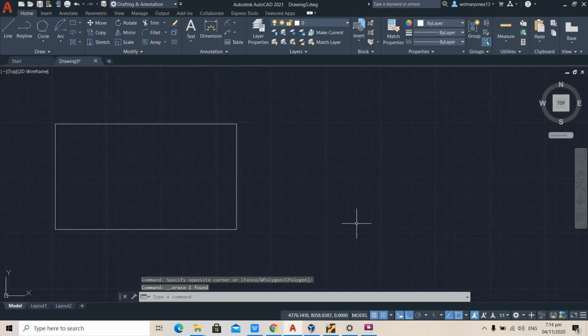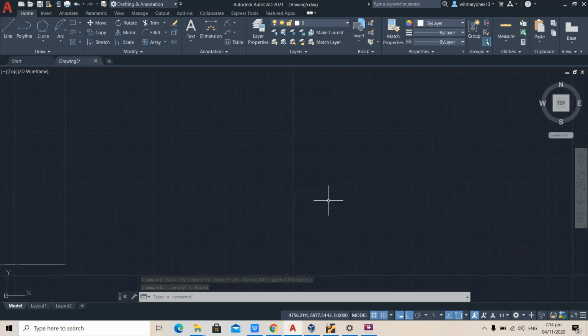And the grid is also helpful. Let's say in snapping, we turn on grid snap. Polar snap is different than grid snap, so let's use grid snap for now because we're talking about the grid. Let's say L, if you want to create a line, as you can see, as I move my cursor, it automatically goes to the intersections of the grid.